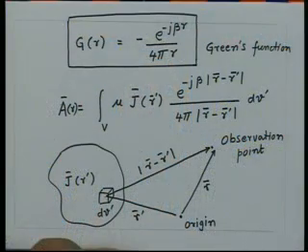That is the smallest, or simplest, current distribution you can think of. However, if you can get the fields for the small current element, then we can visualize any other current distribution as a superposition of these small elements. If I have a structure, I can divide it into small current elements, and then simply applying superposition, if I know the fields due to one current element, I can find the fields due to all the current elements, and I get the electric and magnetic fields for any arbitrary current distribution.